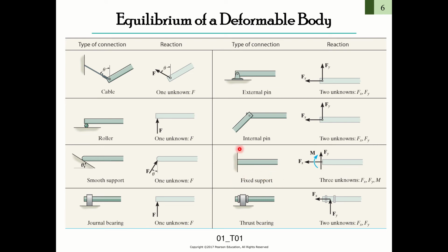This end of the body does not allow any displacement, any movement, so it will have the vertical and the horizontal force to force the displacement equal to zero, and also it will have the moment.